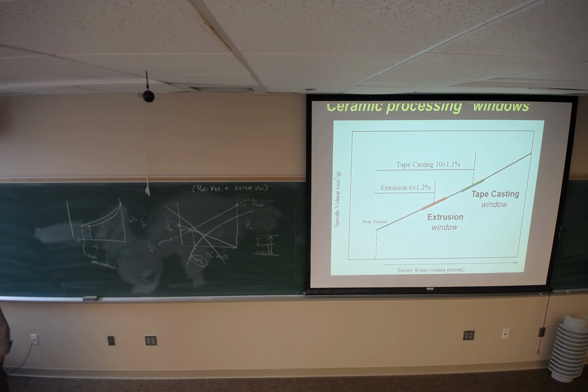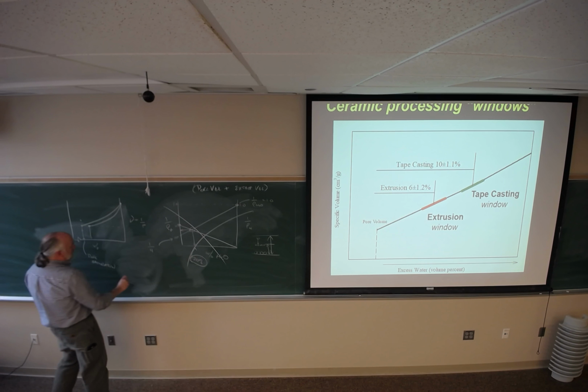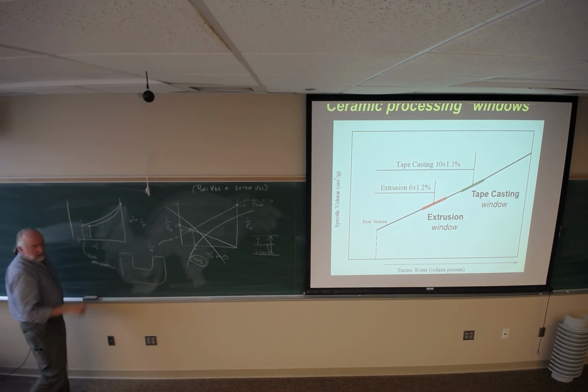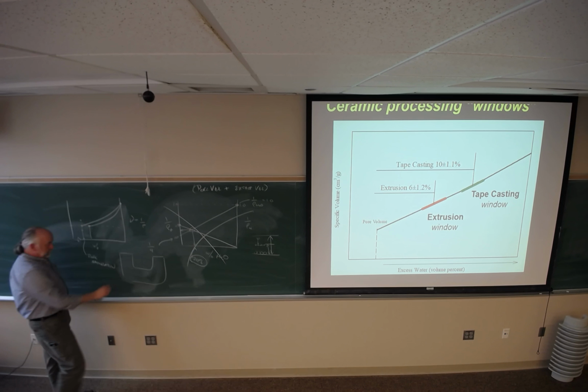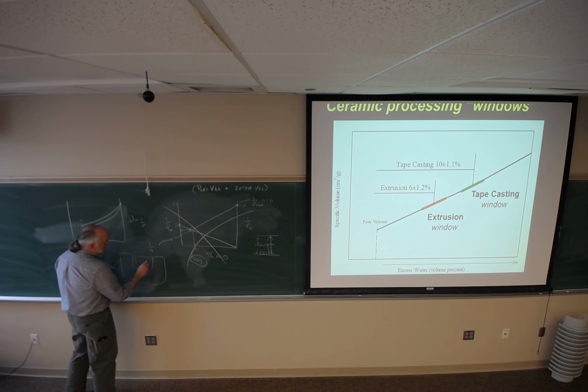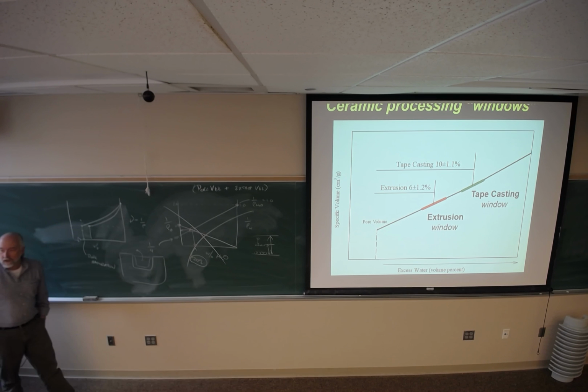So, make a slip cast sample, right? And let's say you're making a simple cup shape, okay? Pour your slip in, and then you build up a wall thickness, right? And then you pour out the excess. It's called drain casting. What contributes to that? In terms of our discussion of specific volume, what do you want to have happen?